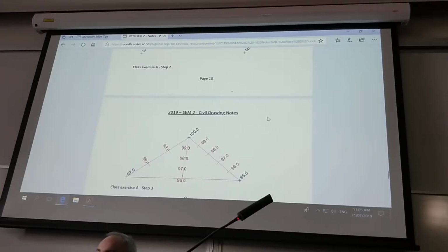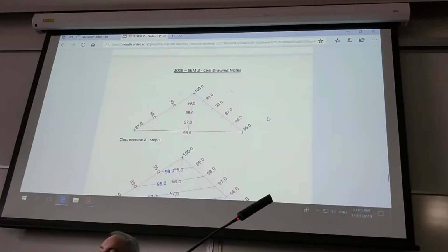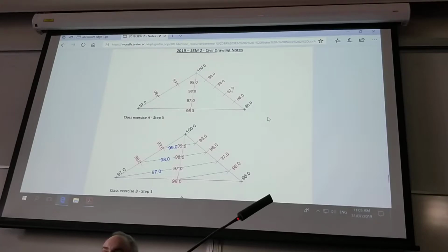So once you've done the vertical line, you can then join everything up and you end up with something like that. So from 3 points, we've ended up getting, eyeballing of course, it's rough, but it's reasonably accurate. We've managed to get 1, 2, 3, 4 contour lines in there. So that's a very quick and easy method.